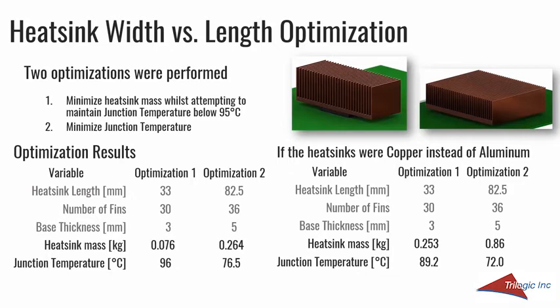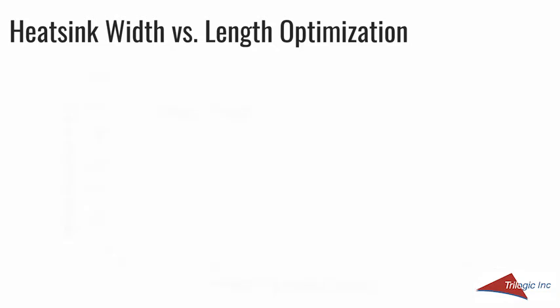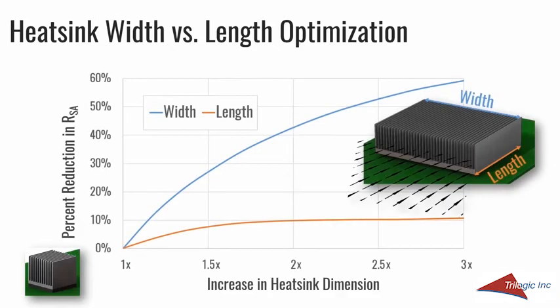I was kind of surprised a little bit. I thought that I might get better performance increase with the higher conductivity material. In this case, it doesn't really warrant the over 3x increase in heatsink mass, probably. That was kind of the one output from the response surface optimization: what are the optimums? The other aspect is trying to study the effect of the input parameters.